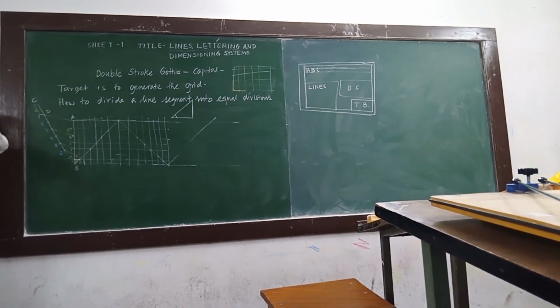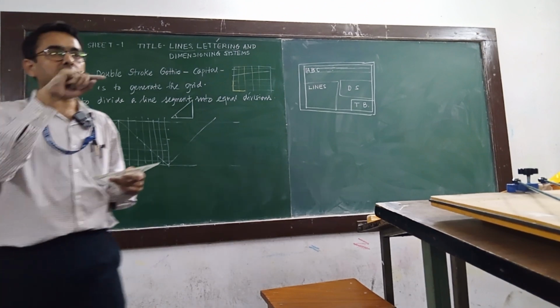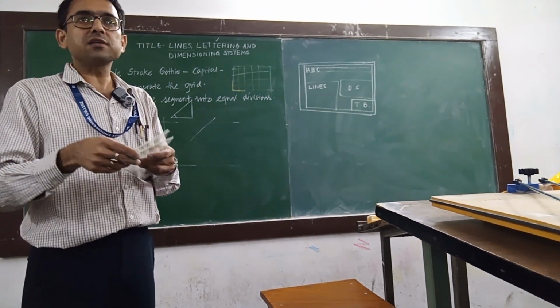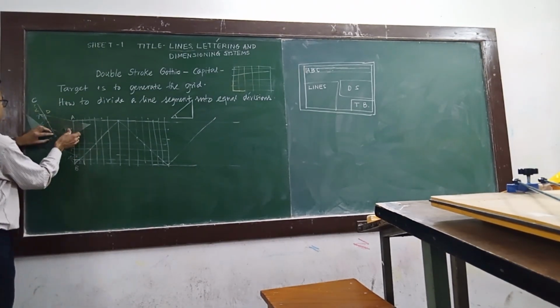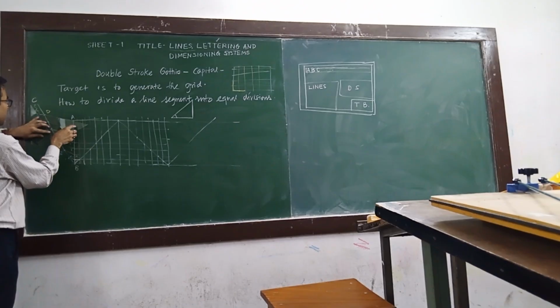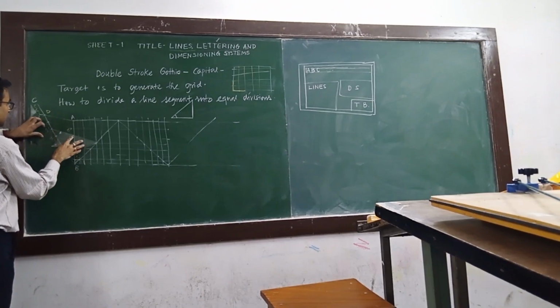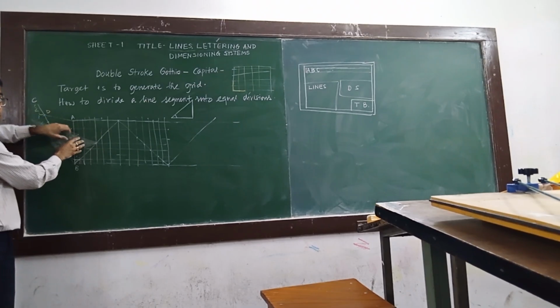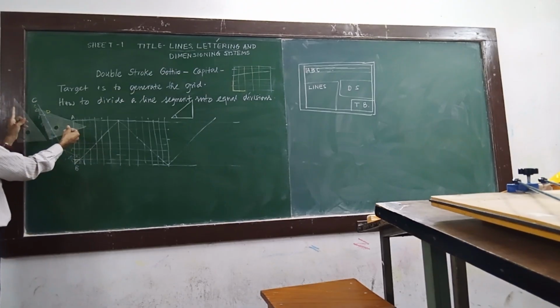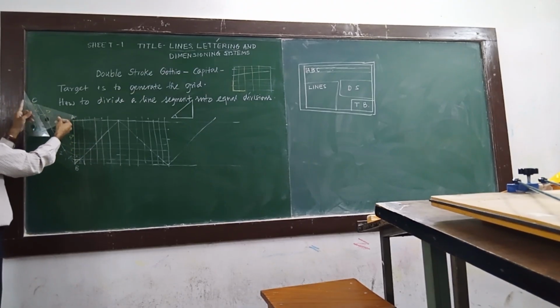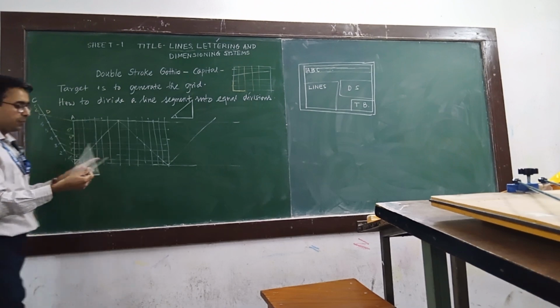As you know from mechanics, if you translate, then it will keep on producing parallel lines. Translation means all the configurations will be parallel to the initial configuration. So simply just slide this and hold this. Clear or not? Is the technical thing clear of drawing parallel lines? Hold this. First set this between 2 points. Then set this with this edge. Then you slide. It will be parallel.